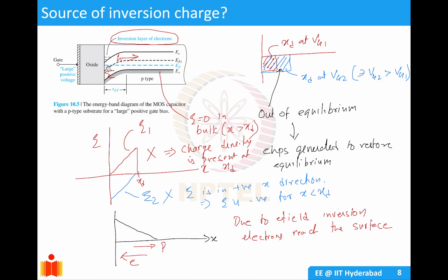How are electrons becoming your majority carriers? So what happens is, because of this band bending, the band bending is now very much higher, and that creates a layer of electrons at the EC and oxide interface. You have a huge accumulation, a huge layer of electrons here.